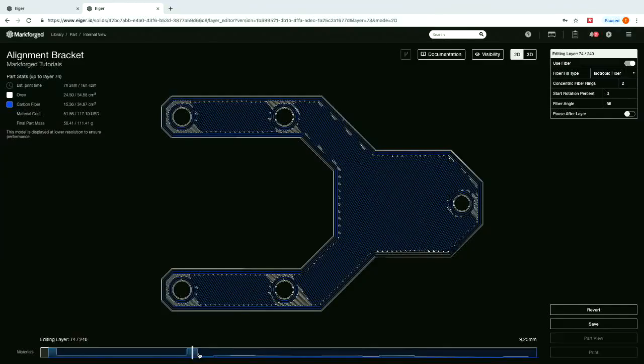Also, someone asked what our largest build volume is. It's 330 millimeters by 270 millimeters by 210 millimeters, which in standard is 13 by 10 by 9 inches. So we don't make giant printers. The calling card of our machines is that they reinforce parts with fiber or they're metal printers. Depending on how big your parts are, making larger tools and end-use parts is possible, but it really depends on what scale you're talking about. One thing we have customers do is make assemblies, for example, sandcast cores and molds, printing multiple parts and then linking them together into a larger tool. So you can definitely bypass that volume constraint.